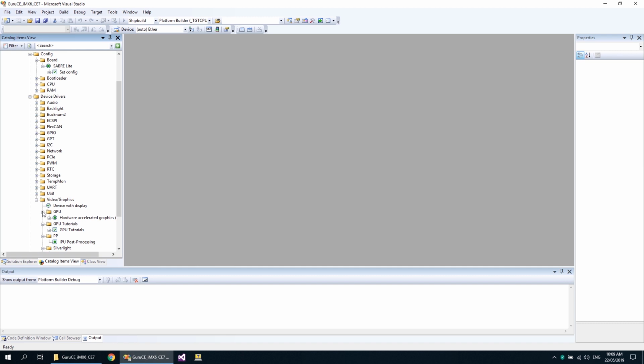The Sabre Lite has display capabilities through the HDMI and LVDS ports, supports touch, USB host and OTG, has 2 serial ports of which UART 2 is used for debug output, has a micro SD card slot, a normal SD card slot, a SATA connector, no RTC chip, supports PWM for backlight control, supports PCI Express, Ethernet, I2C, GPT, GPIO, FlexCAN, ECSPI, and contains an SGTL 5000 audio codec. The Sabre Lite has 1 GB of memory and is fitted with an iMX6 quad processor.